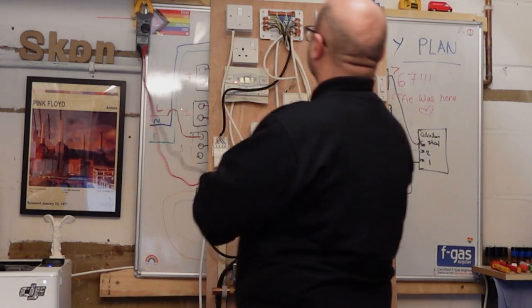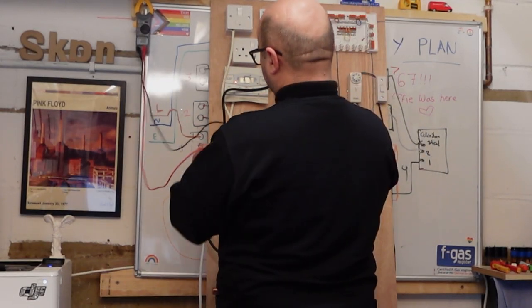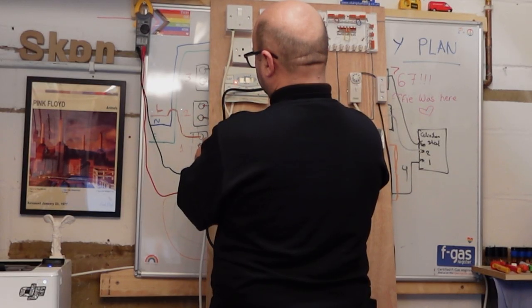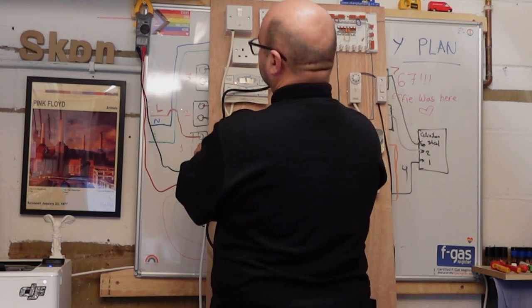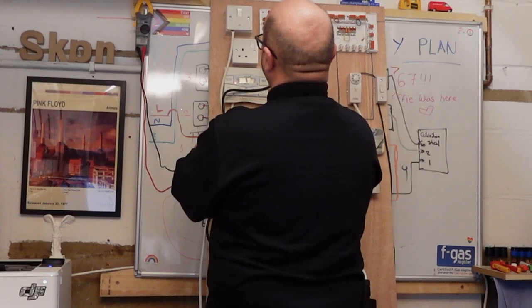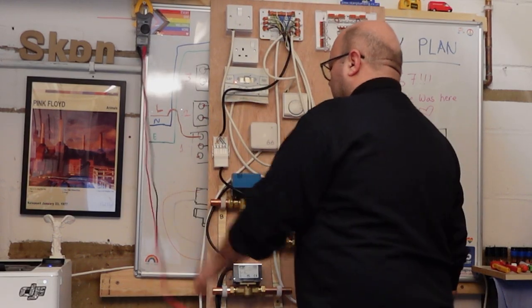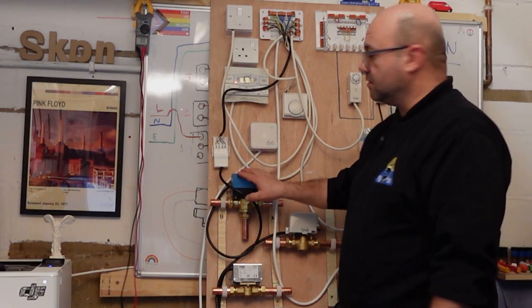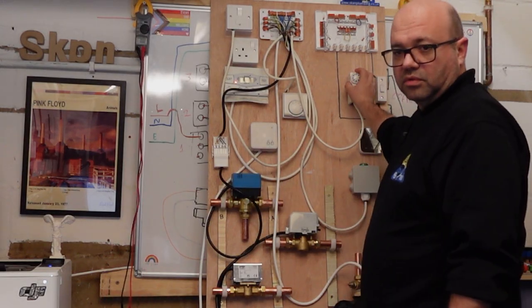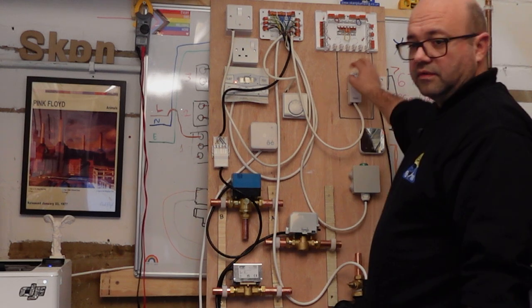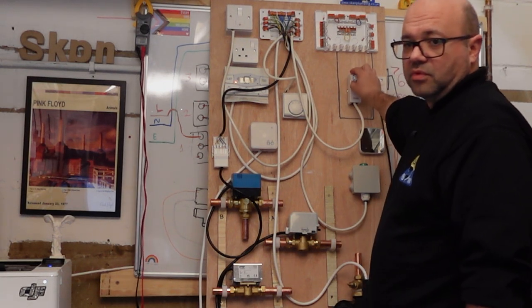We have the voltmeter ready. And then we test between neutral and orange. We don't see any power. Two things could happen. The valve seized, or we didn't call for hot water. So we go to the thermostat to make sure we call for hot water.